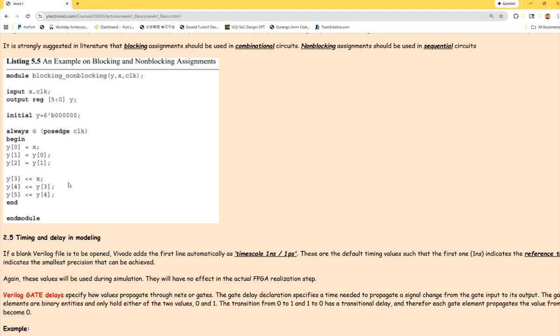No, if you run it faster, the power consumption will be higher. But the thing is, it's running 1 volt for the core because the channel length is smaller, the threshold voltage is lower, and the Arduinos are probably 5. So the VDD is higher, so the power consumption is higher for Arduinos, and it's not able to run faster. So these are all the trade-offs between choosing different technologies for certain products.